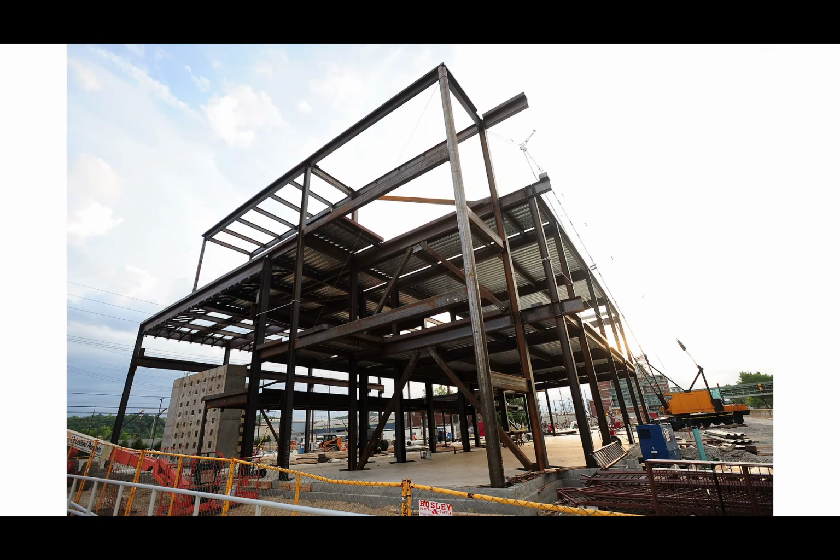One of the things I do like to point out about the bracing system, so if you look here, this is a view of the building, and you can see these inverted V-looking braces right here. One of the things that's worth mentioning is that you actually don't put lateral bracing everywhere in a building. You just put it where you need, okay? So to make the point, let me give you a different example.